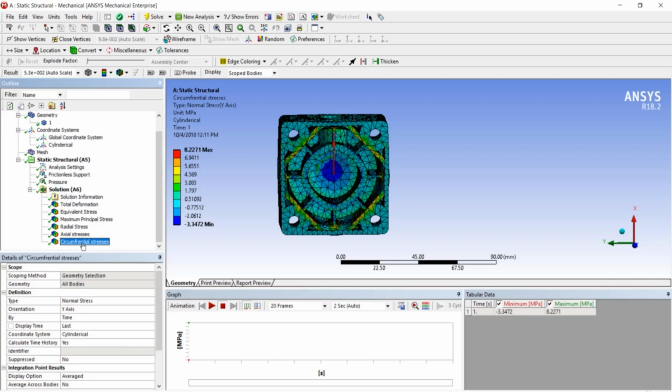Then according to the problem, we need to find the directional deflection of that circular surface and find out whether it is going to exceed the 10 micrometers mark or not. Already by using the total deformation, we have a specific idea that it hasn't crossed the 10 micrometers mark, but we are going to do that also in the next lecture.